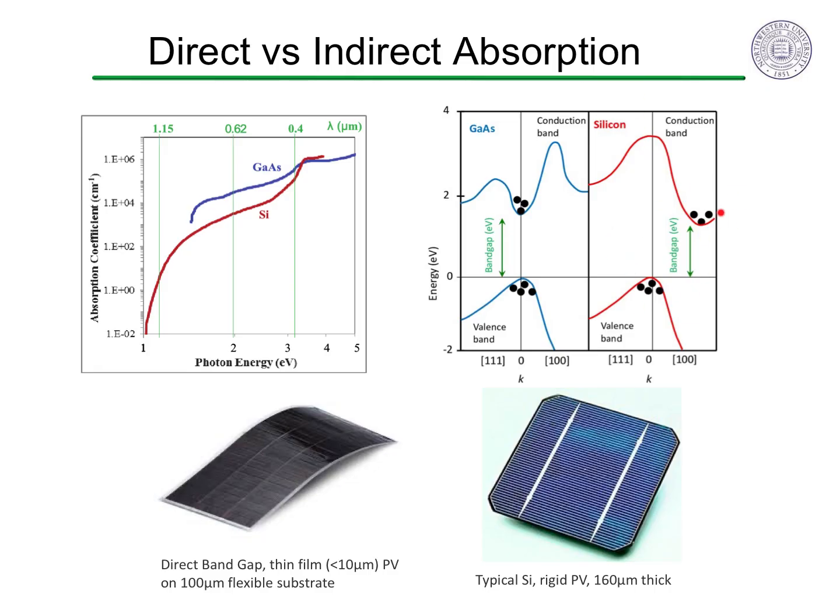Silicon with an indirect bandgap has low light absorption, so the devices need to be thick to absorb all the light efficiently. Typical silicon photovoltaic cells are around 200 microns thick, which makes them brittle and fragile. Direct bandgap semiconductors have a much higher light absorption, enabling thin film photovoltaics. The semiconducting film is only a few microns thick, which makes them flexible and so less fragile when deposited on a flexible substrate.